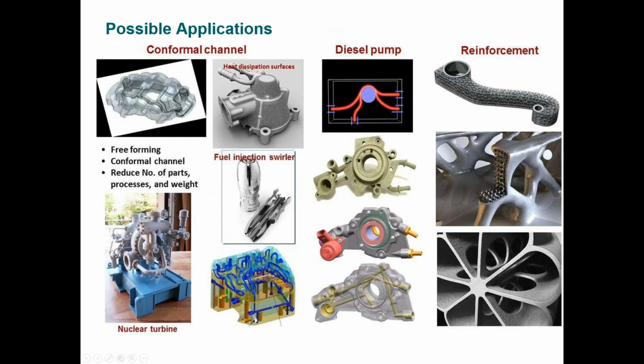Anyway, possible applications, as you can see here, can involve replacement of design or combination of materials and design. For example, the need for heat dissipation or rapid mixing or exposure to chemicals or corrosive environments, or simply lightweighting and reinforcement. As shown here, 3D printing of metals or ceramics has much promise in terms of replacement of traditional molded or casted parts. And of course, the advantage of 3D printing is the ability to make complex designs, which cannot be approached using traditional methods of casting or molding.